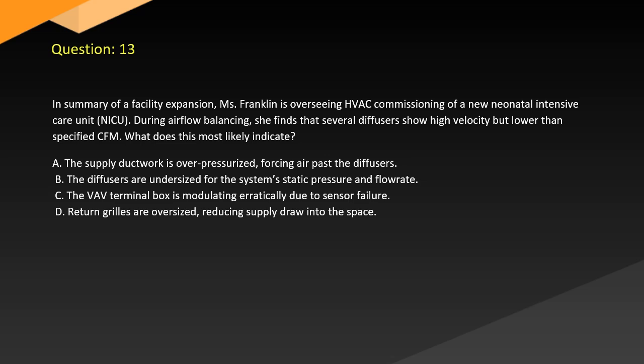A. The supply ductwork is overpressurized, forcing air past the diffusers. B. The diffusers are undersized for the system's static pressure and flow rate. C. The valve terminal box is modulating erratically due to sensor failure. D. Return grills are oversized, reducing supply draw into the space.